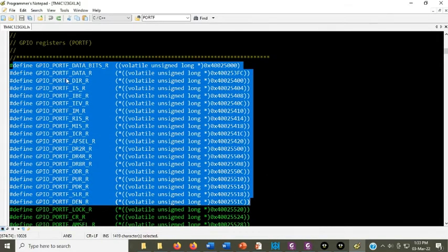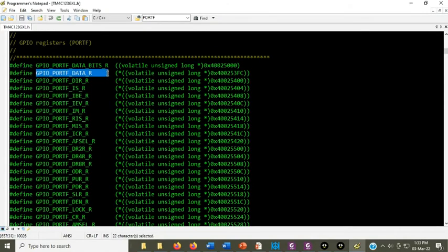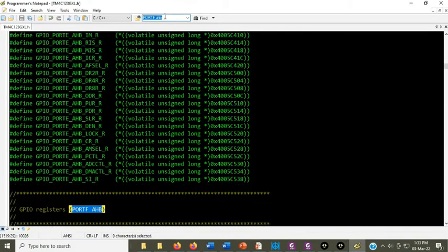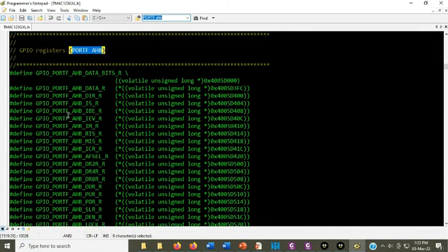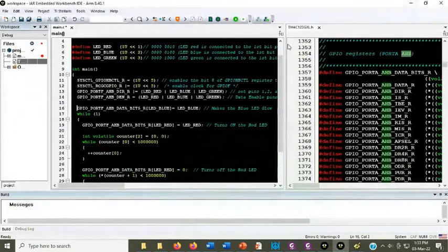These are normal registers. So in the past, we used these registers. Now, if you need AHB, you can just go here, port F AHB. Okay, and you can come to this block of registers which are there for the high speed bus. Change the values for those particular registers, copy paste the registers, and done.